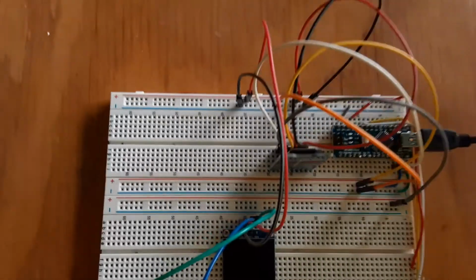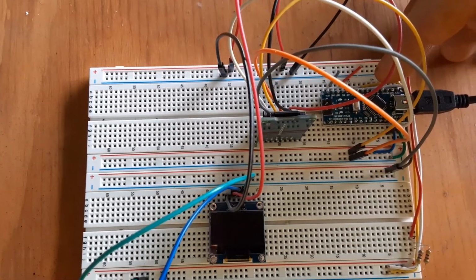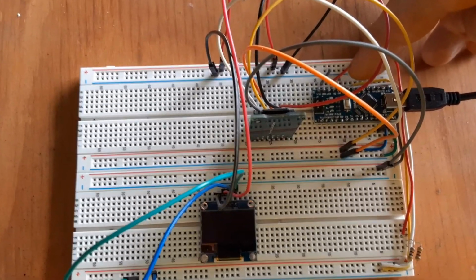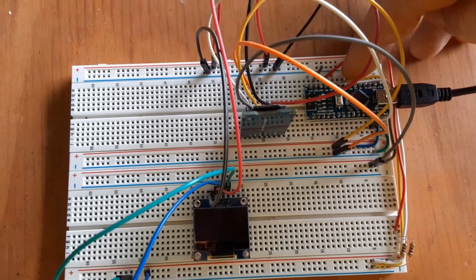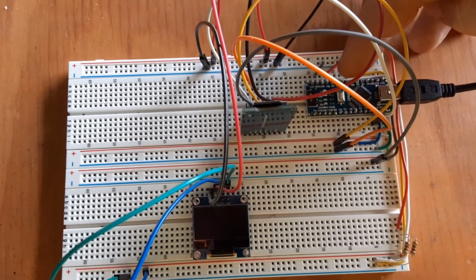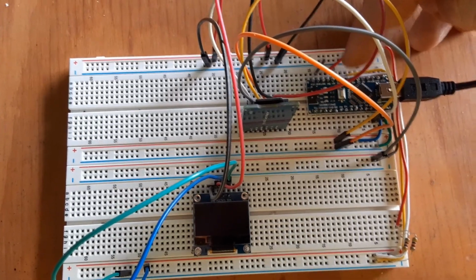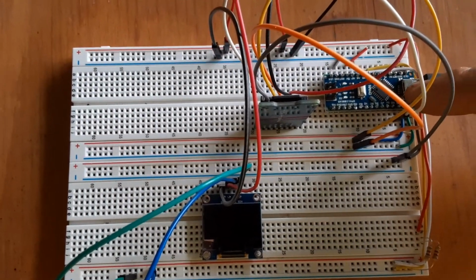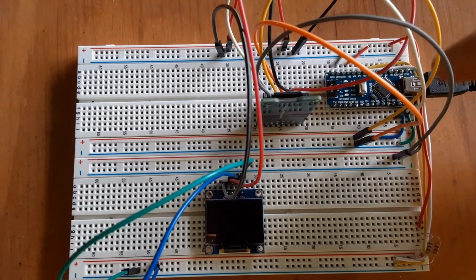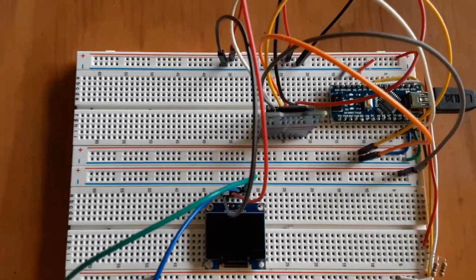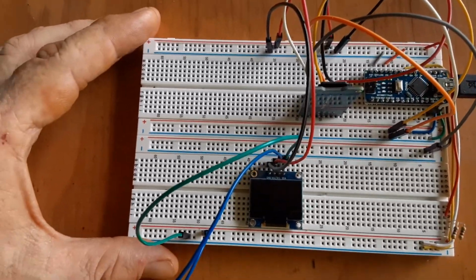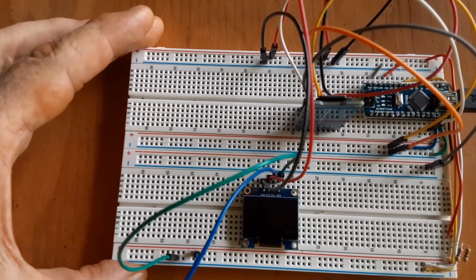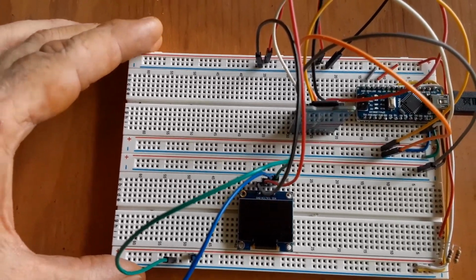Okay, so like I said, the Atmega 328 put onto a PCB big enough to work with leaves us plenty of room to do some extra stuff too, such as hook up I2C. By default, it goes to analog pins 4 and 5, and the SPI goes to pins 11, 12, and 13 for the MOSI, MISO, and clock. And then you just choose any other pin you want for chip select, or some other way to power the chip select.